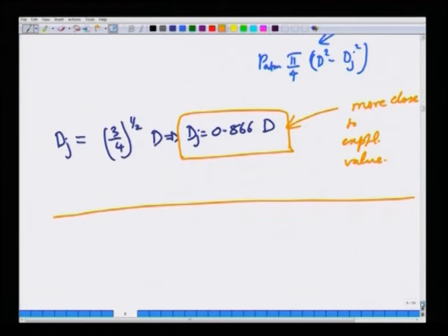Now, I am going to go to differential balances of the same three quantities, but before I do that, let me also say a few words, repeat a few things that I said on and off about integral balances. That is, they are fairly simple to use because of the fact that they can be written across entire equipments. For example, you can write an integral balance about a pump or a compressor or involving pipelines and so on. But the price that we pay is that we need to have information about the losses, viscous losses, which have to be either obtained from experiments or they have to be obtained from a more fundamental theory.